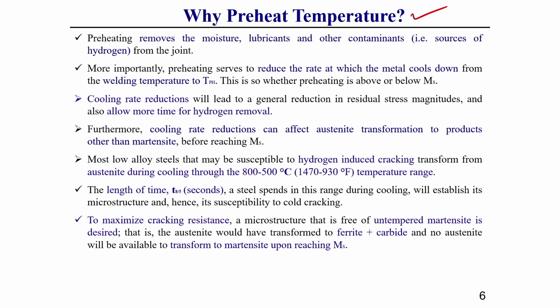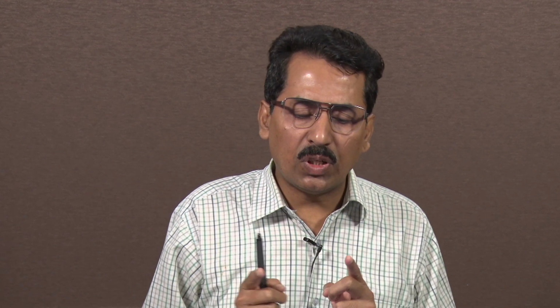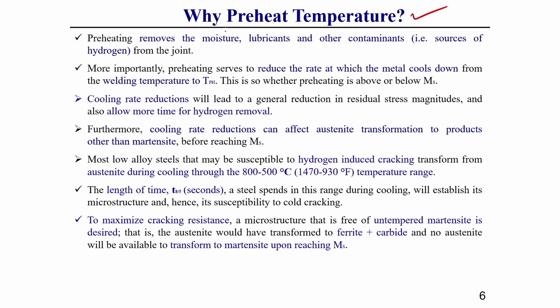Why is this preheating temperature required? Because preheating is very essential, as it has a lot of effects. One of the most important effects is that preheating removes moisture, if there is any moisture in the weld plate. It also removes lubricants and other contaminants.